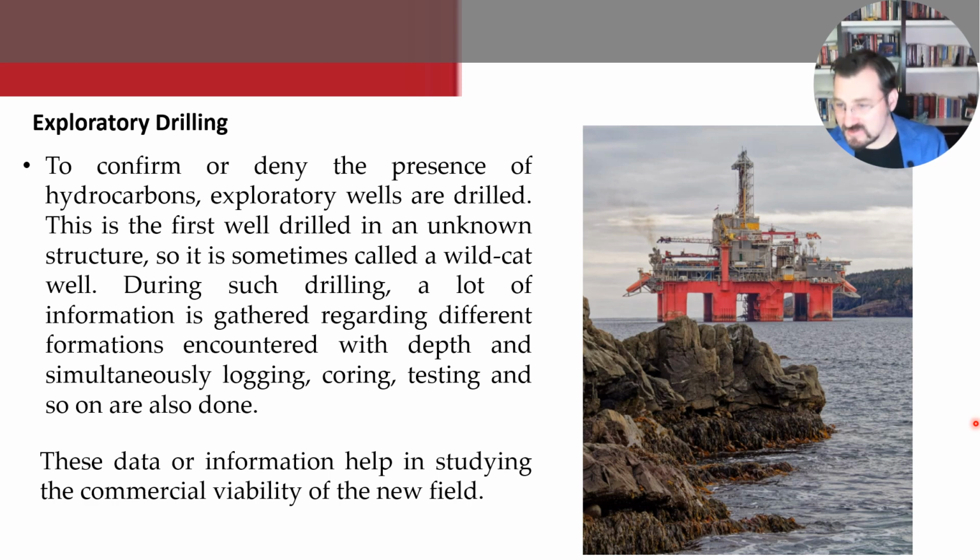Here it is not advisable to deploy a fixed platform, because in the case of non-commerciality, the platform has to be abandoned. Therefore, in that scenario, mobile units need to be used, like a jackup rig or a submersible unit or floating units. So in wildcats, it's better to use drilling ships, offshore drilling ships, and some semi-submersible or jackup rigs.